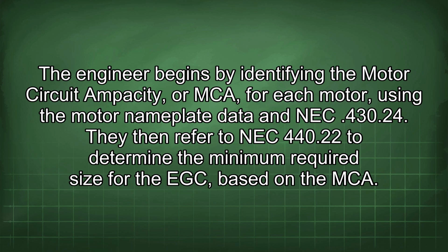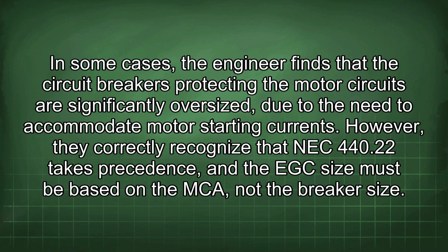They then refer to NEC 440.22 to determine the minimum required size for the EGC based on the MCA. In some cases, the engineer finds that the circuit breakers protecting the motor circuits are significantly oversized due to the need to accommodate motor starting currents. However, they correctly recognize that NEC 440.22 takes precedence, and the EGC size must be based on the MCA, not